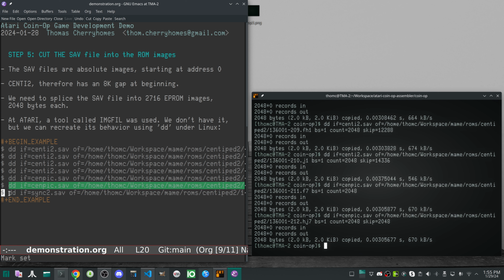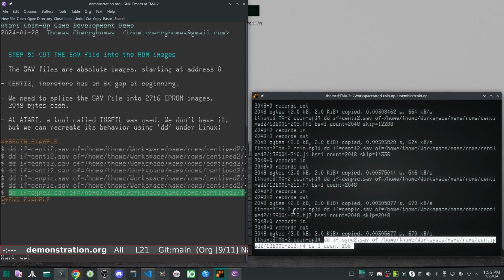And we also need to do the sync prom. This is a teeny tiny little bipolar prom here that's used as a finite state machine for the IRQ handler, among other things. If you ever wonder where Steve Wozniak came up with the idea of using a prom as a state machine for the Disk II sequencer, no, he did not pull that out of thin air. Coin-op guys at Atari were doing it before he did. Let's just put that there.